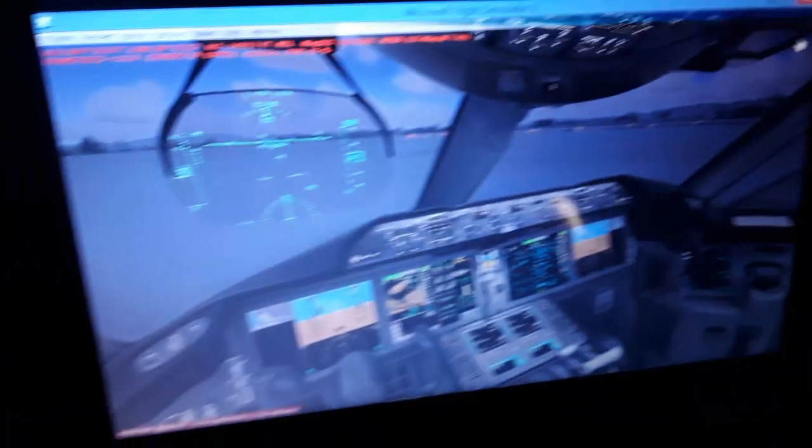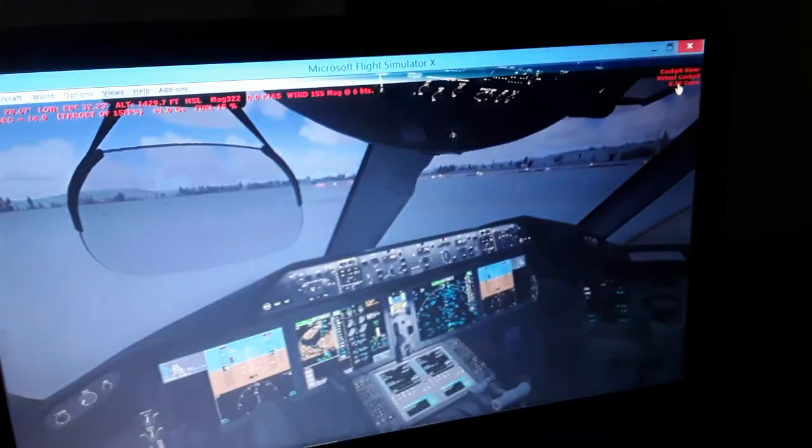Also, as we fly, we burn fuel, and the center of gravity shifts and is calculated automatically again. This also affects the mean aerodynamic chord position that I told you about, where the maximum aerodynamic lift occurs, and also where the stall will begin for a given angle of attack in flight, at an airspeed that either increases or decreases.